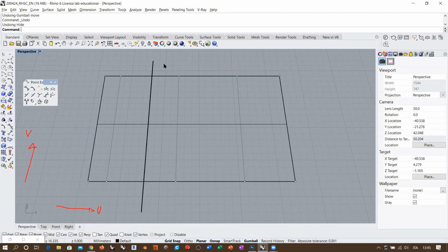On the other hand, if I want a more complex deformation on this part here, I always need this to be a span division or a knot line, but I need more spans in this area if I want a more local deformation.